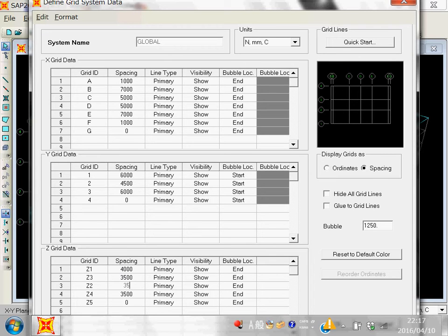Let's see what happens. Should we consider the depth of slab? Dead load of slab, depth of slab, actually these are the center to center heights. You can calculate. For example, if in the drawings you have the clear height, that is known as ceiling height, which is the height from the slab to the floor. So if that is the case, you must add the slab depth into the ceiling height to get the center to center height.